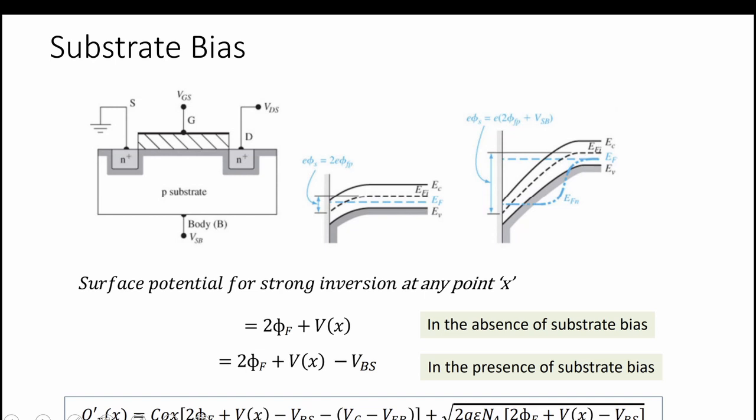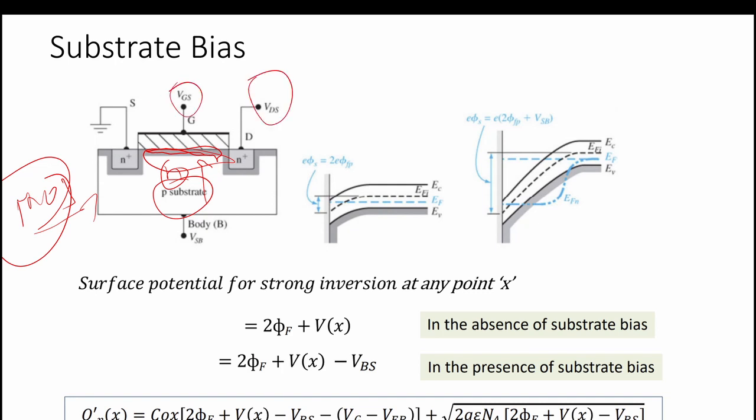Okay, this is the MOSFET. So this is an n type MOSFET, because the substrate is p type, so after inversion there will be a creation of the n channel. Initially, when we haven't applied any bias at VGS and VDS, there is a depletion region which is in equilibrium.